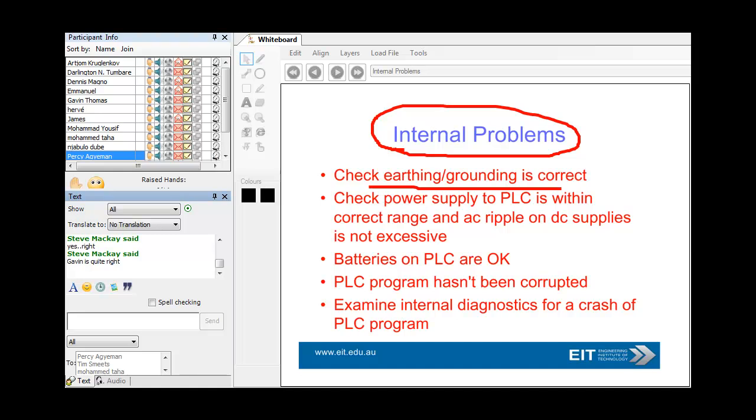You should always, and I've learned the bitter hard way, try and use RS-485, but even RS-485, which is a really great communication standard, you can actually have subtle problems with common mode voltage, which means that your remote racks drift up in voltage and you have a problem. So really, at the end of the day, the best way to get rid of all your problems with communication links is try and use fiber if you can.